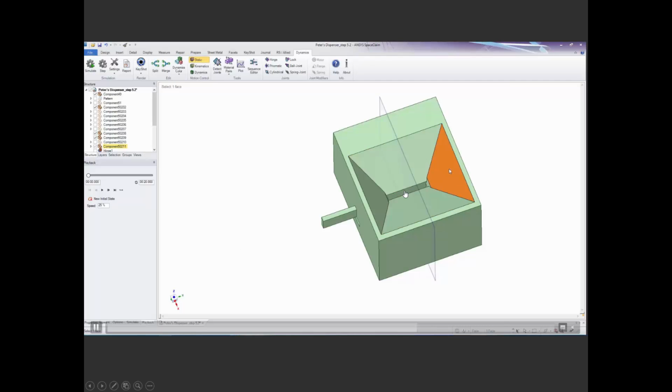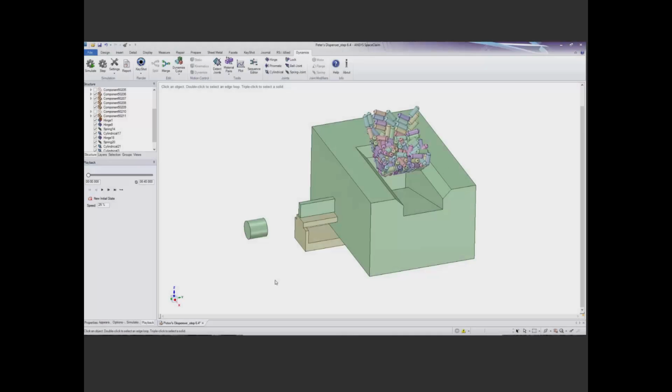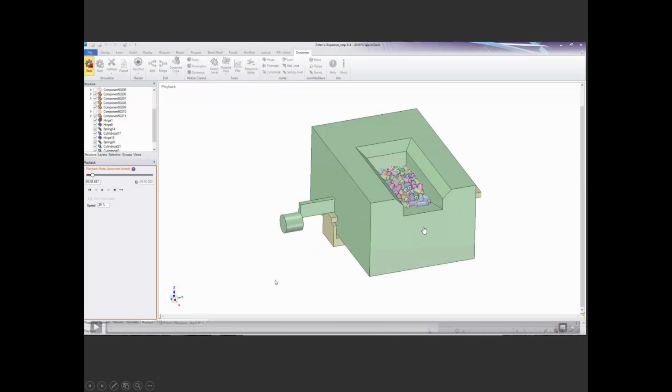Anyhow, we still have this problem of the pills not wanting to fall down into that narrow gap very reliably. And I managed to come up with a pretty good solution to that problem. Principle where we have this plane that is slanting just a little bit down towards the opening down here. And this is also surrounded by these three vertical walls. And as a result, we have eliminated virtually all external forces on the system, except for the vertical pull of gravity. So we have effectively removed the circumstances that made it possible for this phenomena to occur, where the pills lock onto one another.